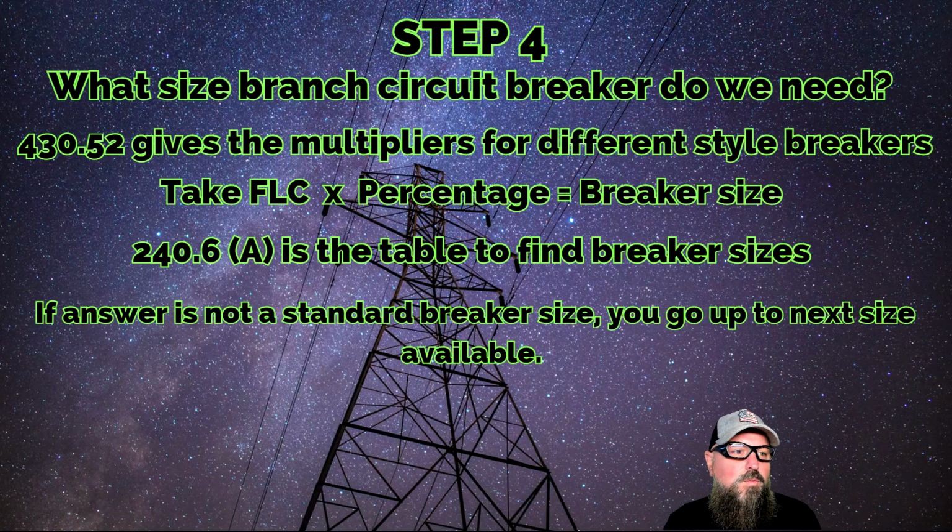So step 4, what size branch circuit breaker do we need? The table we're going to use is 430.52, which gives the multipliers for different style breakers. So you take the FLC times the percentage, and it will equal the breaker size. Then you go to 240.6a, and this is the table where you'll find breaker sizes. If the answer is not a standard breaker size, you go up to the next size available.